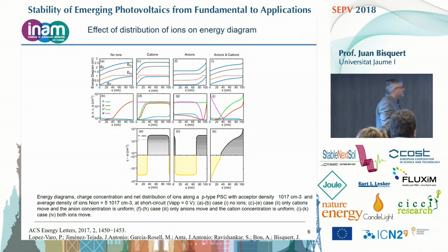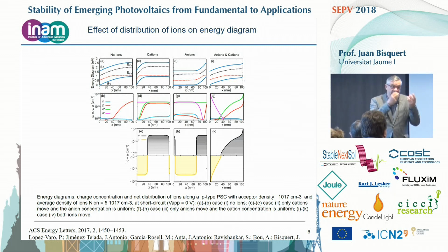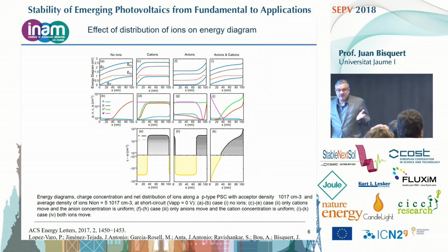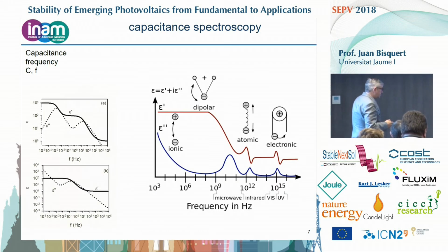For example, this is a little bit obvious when you know it, but if the mobile ionic density exceeds the intrinsic doping density, then you will be controlled by voltage. You can invert the Schottky barrier from one side to the other, because these moving ions can control the depletion layers, so it will be extremely complex. This is something we can imagine.